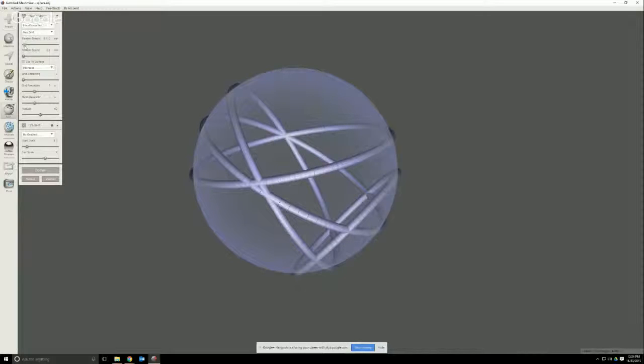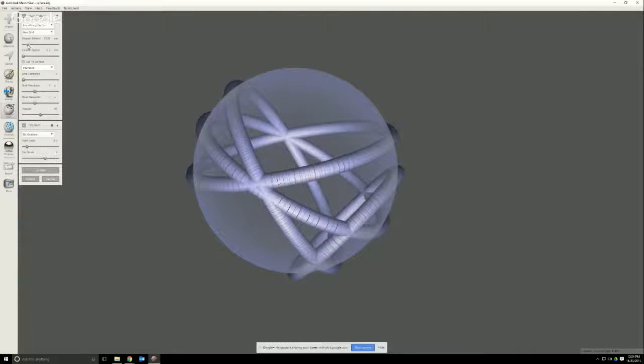If you're doing this for 3D printing, as an example, if you wanted to 3D print this in metal, you would go to a company like Shapeways, and Shapeways would say that they cannot print any wires like this that are under, let's say, I don't know the exact number, 1.8 millimeters. So you would say, okay, well, if Shapeways needs 2 millimeters, let's just click on this and make this 2. I click that and press enter. So now, as long as I don't shrink anything, this is all printable by Shapeways in metal.